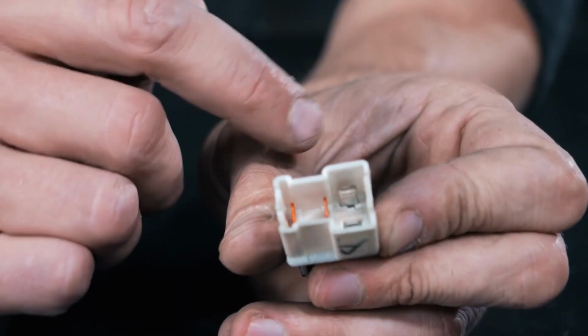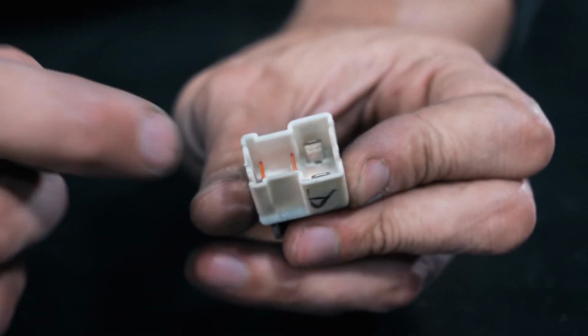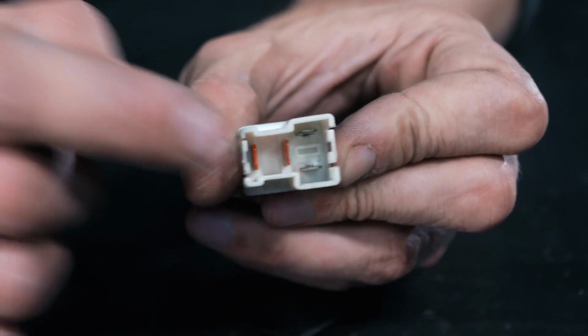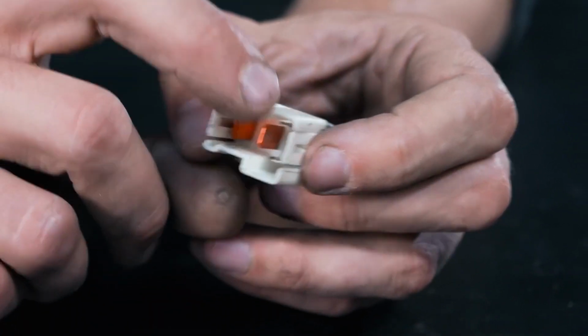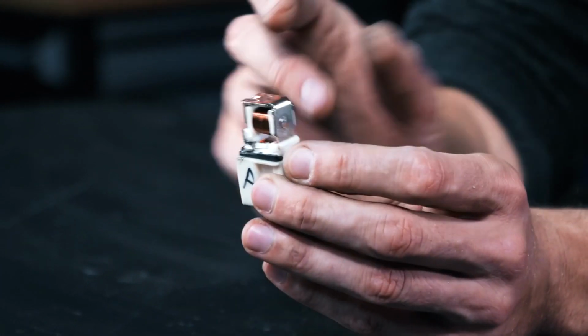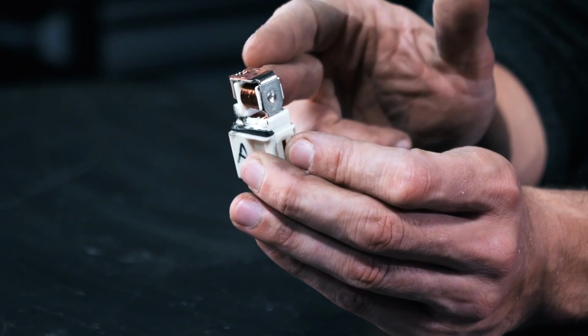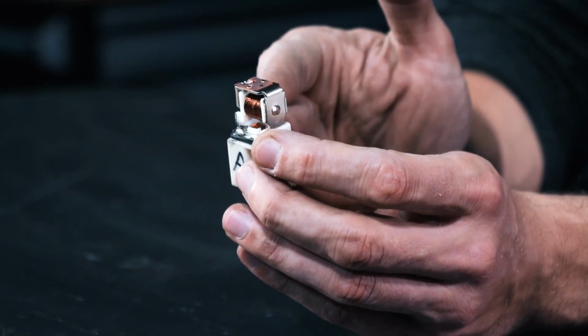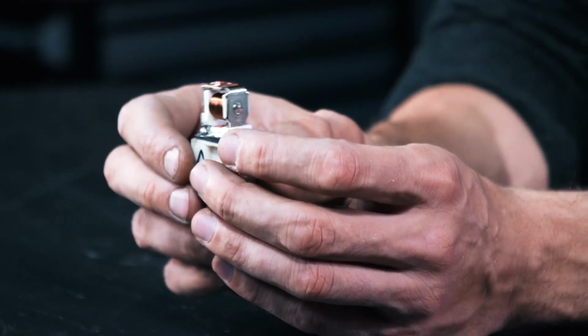And that pulls the armature into contact with a terminal. So what we have is, if we look at the underneath, we have 2 small terminals which control the current running through the coil, and then we have 2 larger terminals which provide the power that is being switched on and off. So those are the contacts, basically. Those carry the high current, so that's the high current side. So as the coil is energized, it pulls this armature towards, makes contact, closes that circuit with the high current running in it, and the high current runs out through the relay.